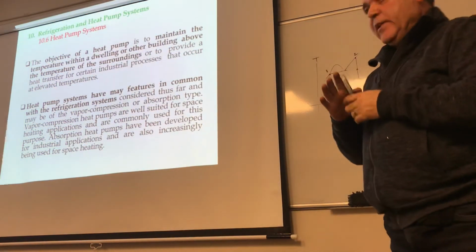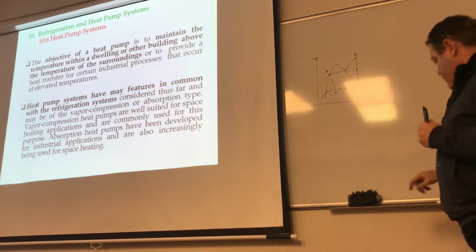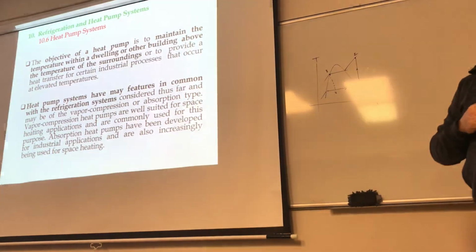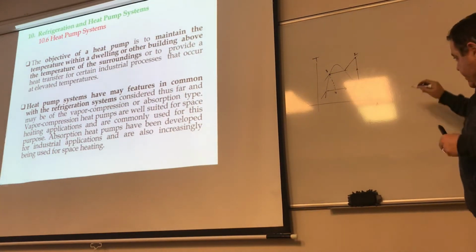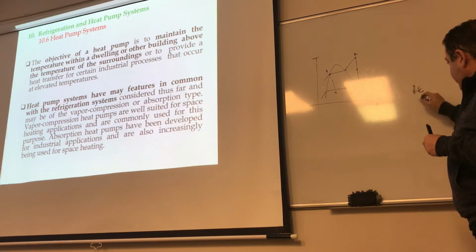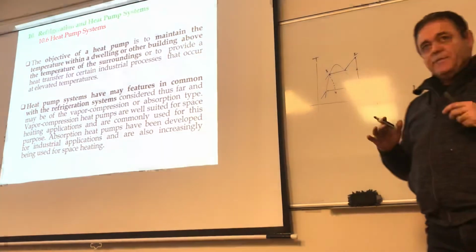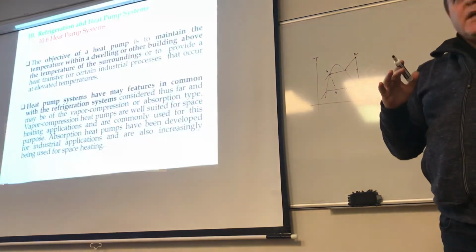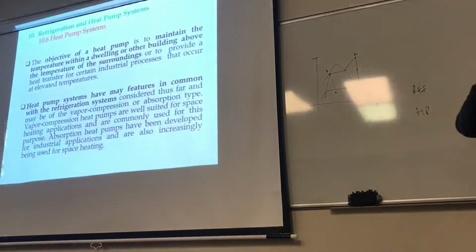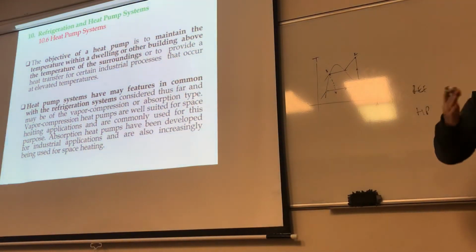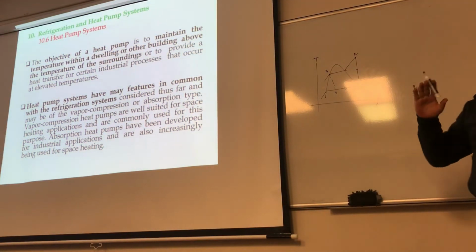In fact, it only gets reflected in one quantity, which is what? Between a refrigerator and a heat pump, what's the only thing that gets changed? The direction of the Q. Well, of course, the direction of the Q. Heating a space versus cooling a space. Not the efficiency, the coefficient of performance. That's the only thing that changed.